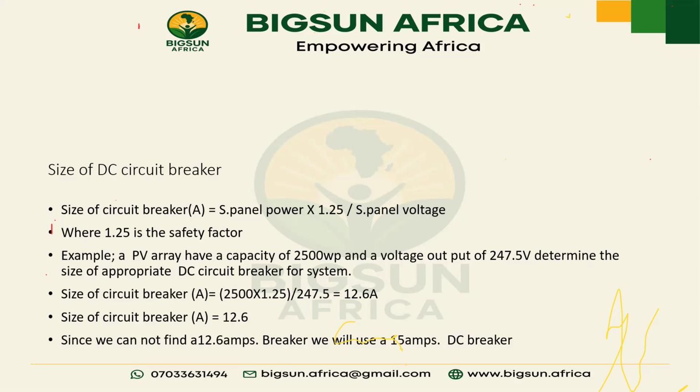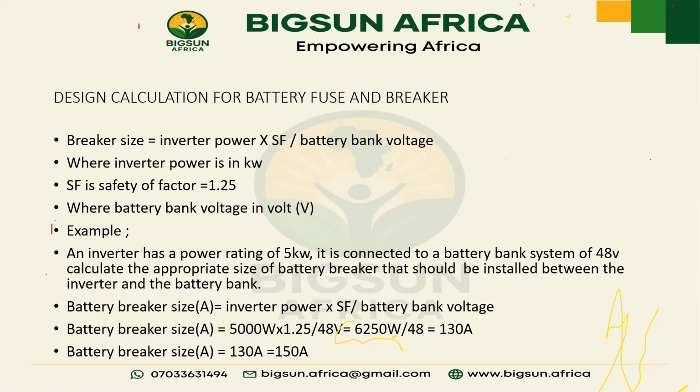Hello, sir, yes, I'm with you. I came across one of my bosses some while ago. I wanted to buy a hybrid inverter for my client, and he said, why shouldn't I go for the transformer-based? His reason was that whenever there is an earth fault or thunder strike, non-hybrid inverters usually get damaged by the charge controller.